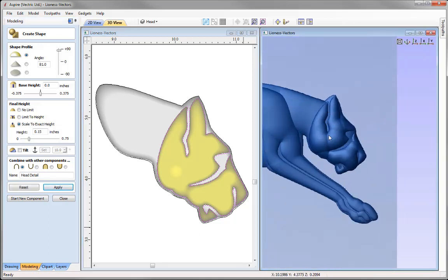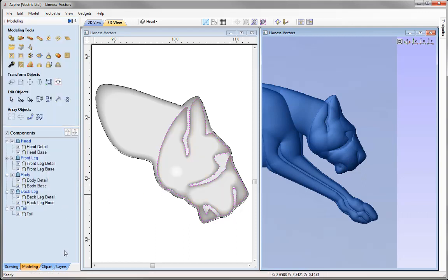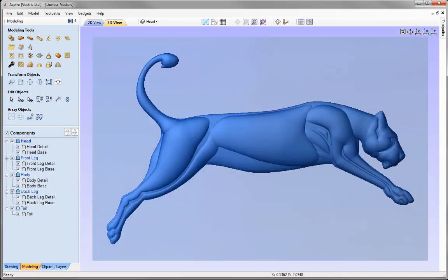And it's quite bulbous, quite rounded, so you might want to just knock the height back a little, so you could bring that down to 0.1, space to enter that in. We might want to do that a little bit more, so we could just look at using the slider. Okay, and that seems to have done the trick there. We're still hinting at all the detail. So we could just simply close that down, and we could maximise the 3D view there.